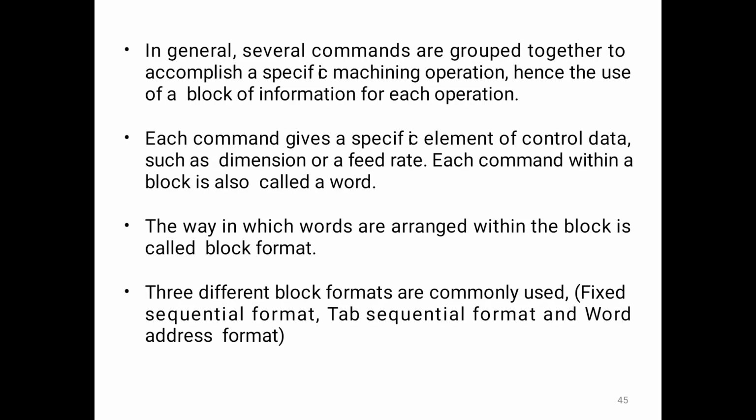Each command gives a specific element of control data, such as a dimension or a feed rate. Each command within a block is also called a word. The way in which words are arranged within the block is called block format. Three different block formats are commonly used: fixed sequential format, tab sequential format, and word address format.